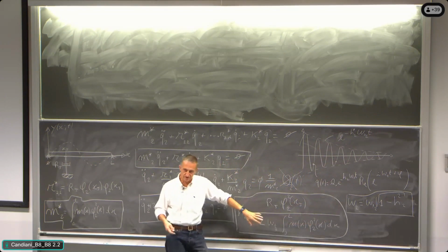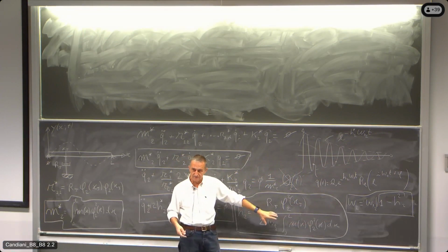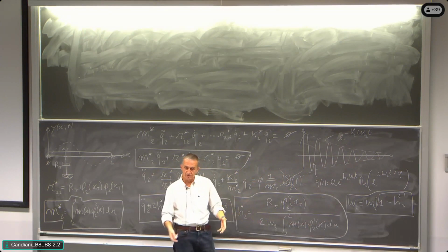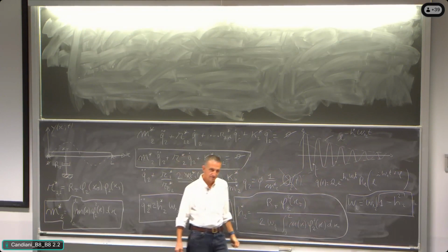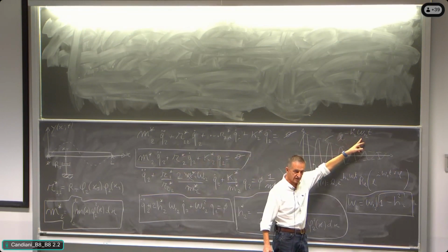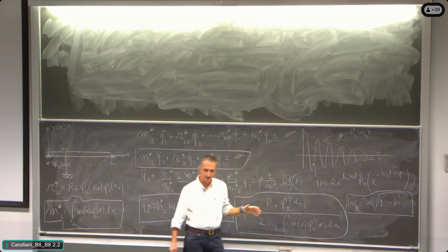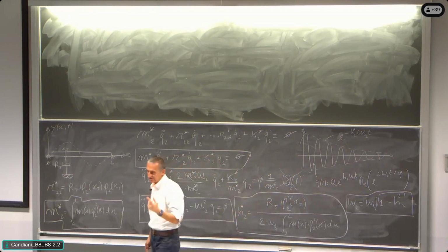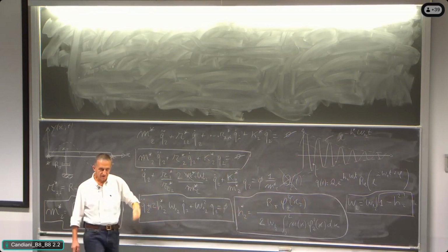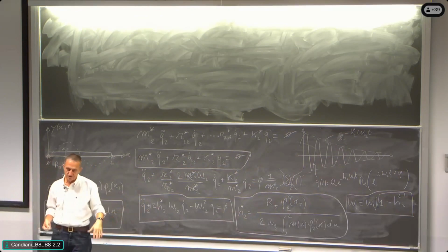So from the quantitative point of view, we must write a number here. We must be able to write the numbers. It is necessary. But in the analytical expression, it is multiplied by the natural frequency omega 0,2. In case we do not remember those expressions, there is only one thing to do: go back to the theory of the 1 degree of freedom system, and redo all the calculation by hand ourselves with the closed page of the book.